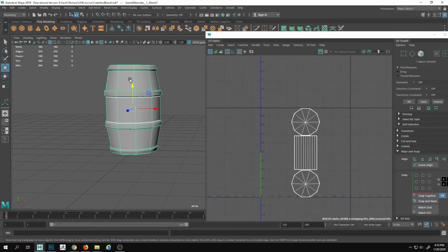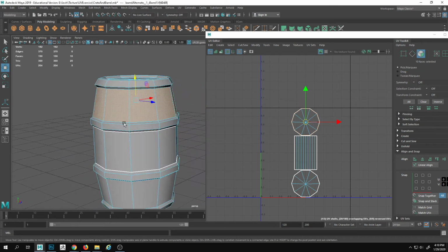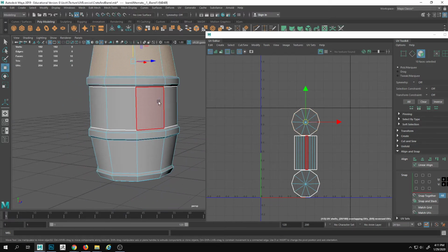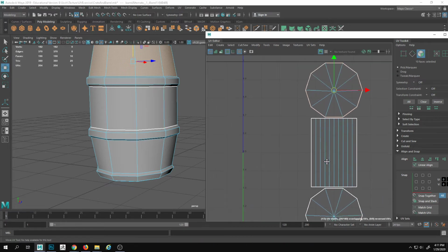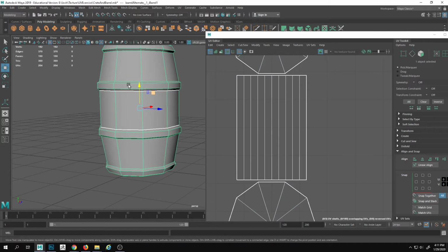Let's look at our poly count. I'm going to drag across just those. It's 20. So that's a 20-sided, no it isn't, it's 10-sided, 10 faces all the way around this cylinder. 20 triangles. That's a lot easier to work with. It also, because it's 10, is an even number, meaning that 1, 2, 3, 4, 5, I can divide this in half if needed to make it repeat. And I'll show you what that means in a second here.